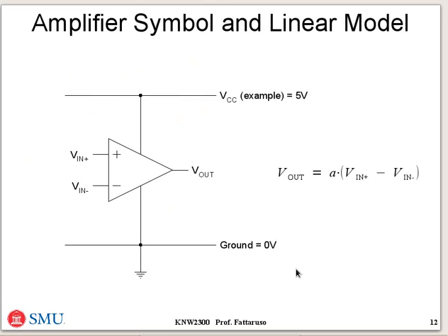So we're going to combine a couple of sub-circuits to make our final amplifier. The first is the integrated circuit amplifier, the op-amp itself, and again we use this triangular symbol. There are two input terminals to a differential op-amp and an output terminal. It requires some power being applied. In this example case, we're running this op-amp off of the 5-volt supply here. And then the other power terminal goes to ground, our reference for 0 volts of potential in the circuit.